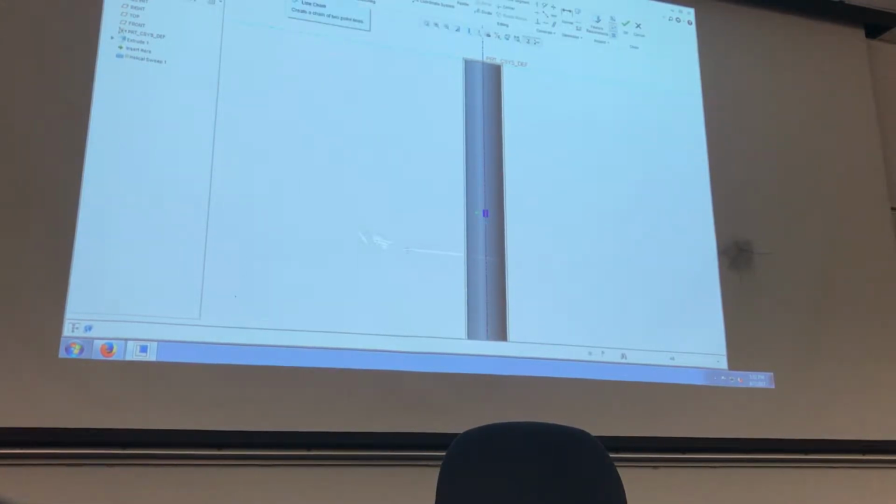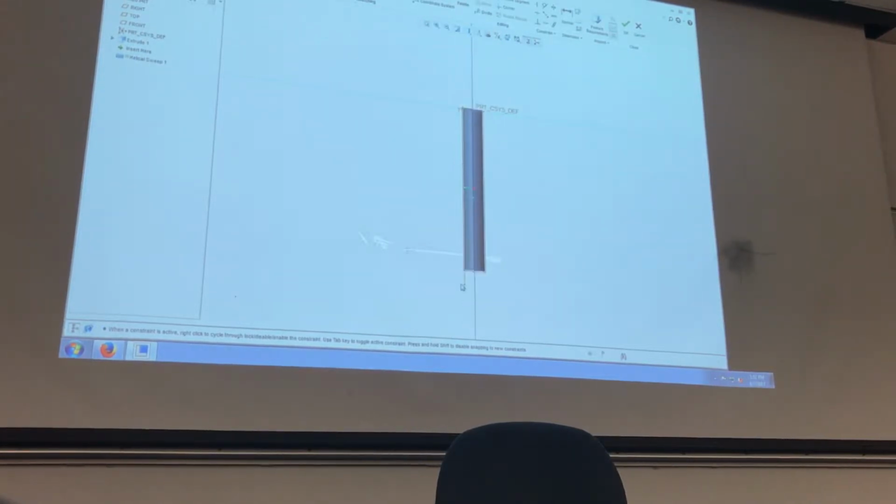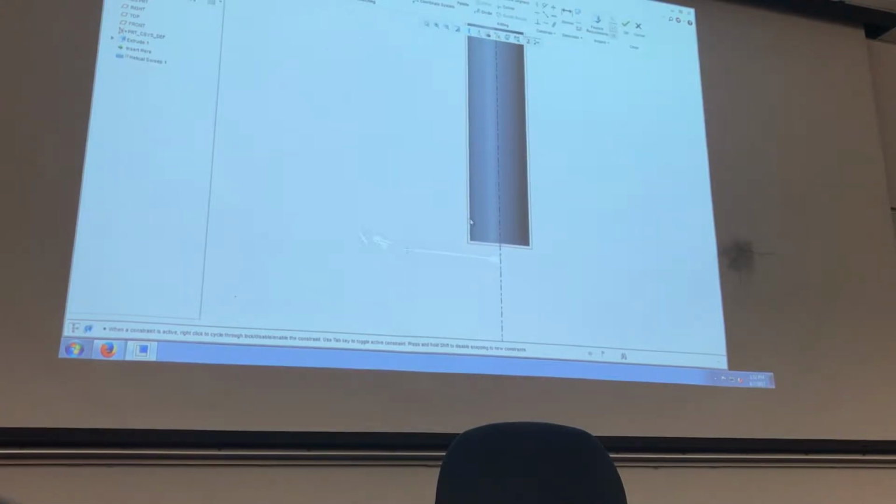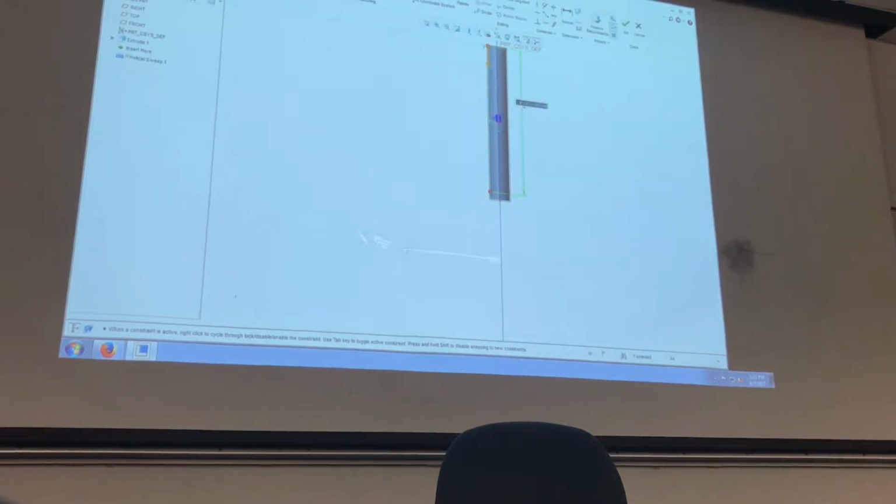The profile basically is what direction is it going to go. So what I'm going to do is take a line, let it snap to that point right here, and I'm going to bring it down to about here. I know that my pitch is going to be 0.05. So this value here, I want to put in at 1.95 or less.